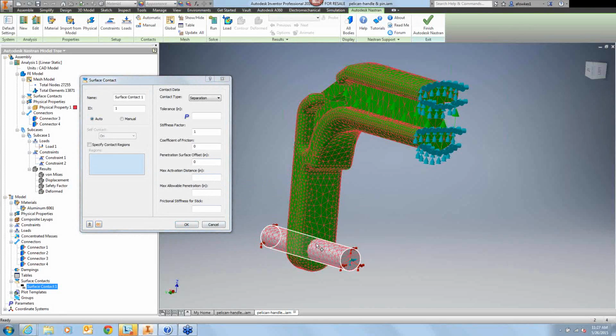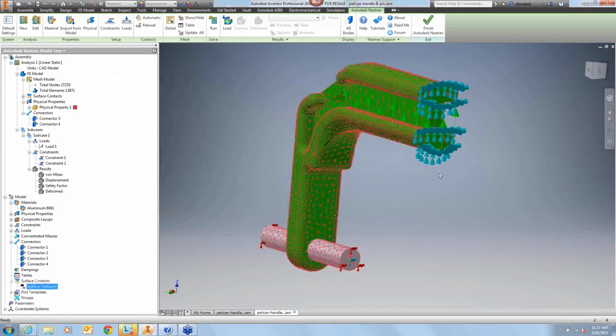That'll basically allow parts to contact when they're within that distance. But in this case, very closely associated nodes, basically the surfaces are flush, so we expect the contact tolerance to be picked such that there's going to be contact initially in the analysis.